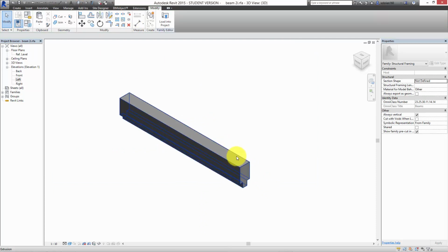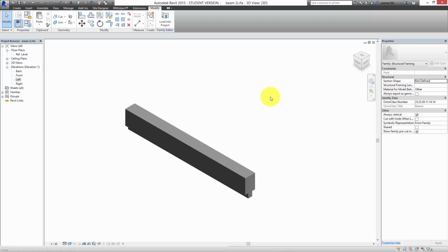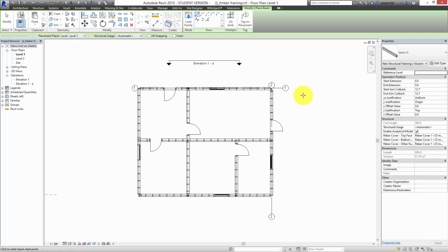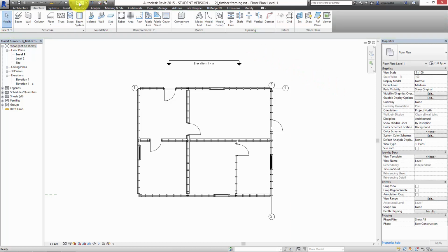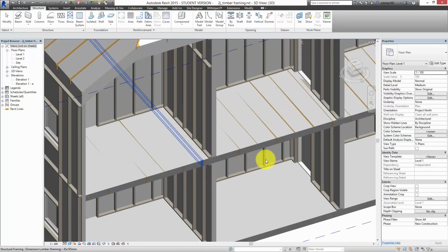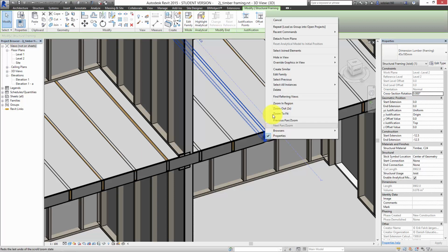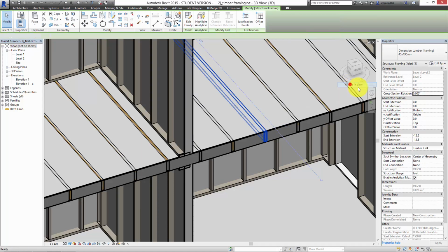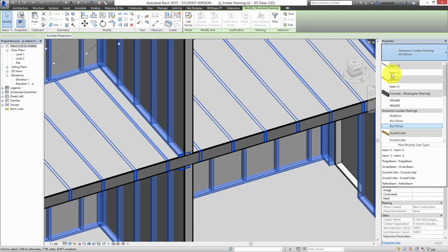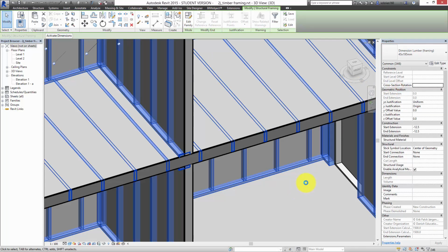Let's say you're making a beam that, I don't know, has cable boxes that you want to align into the beam or something. So you might get a precast beam designed that's shaped in a specific way. So once you've done that, what's it called? It's called Beam 2i. You can load it into the project. And you can see it turns up over here, Beam 2i. So like everything else, you can go in and select the same type of element, which is a beam. I'm going to select this one, select all the instances in the view, and I can change them to Beam 2i, like that.